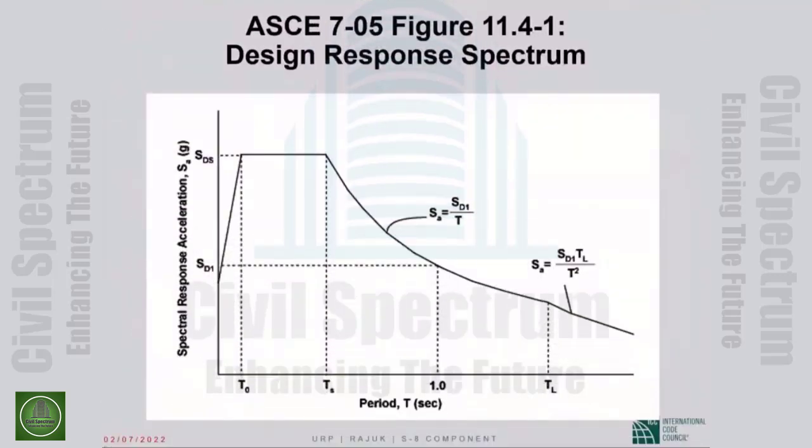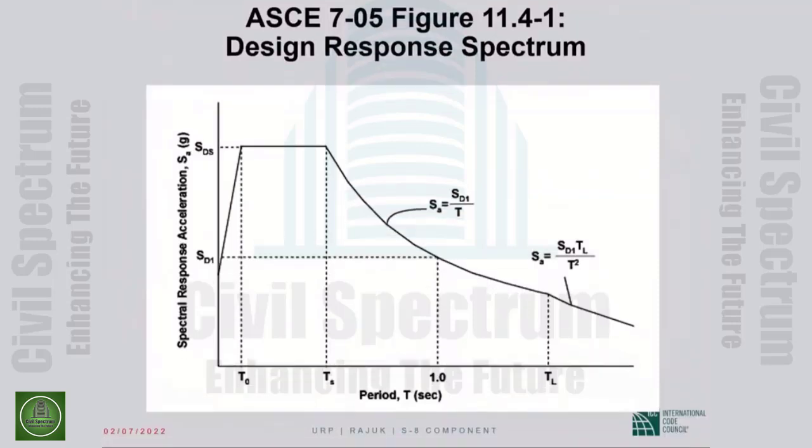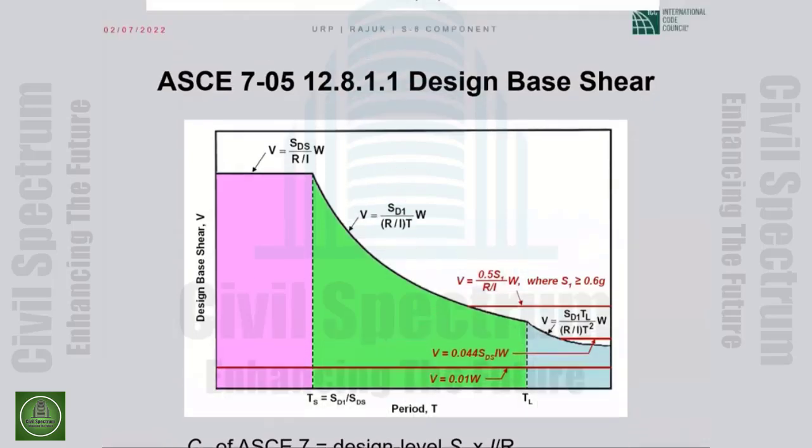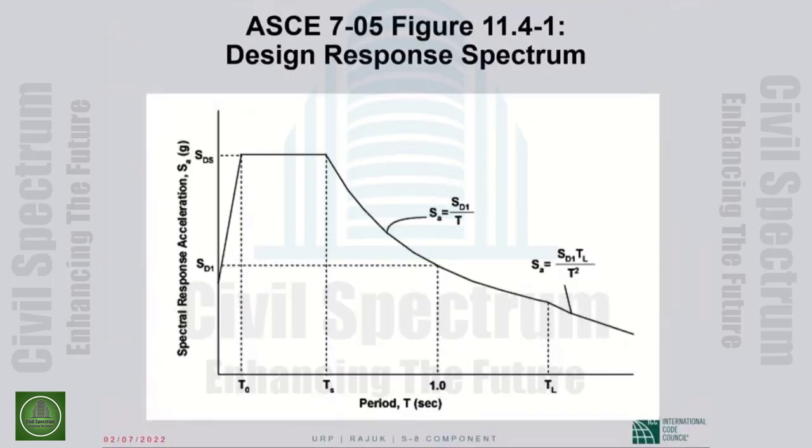Okay, the design response spectrum of ASCE 7 you have seen 10 times by now. The point is, the reason I showed you again is when we do the equivalent lateral force procedure, we modify the elastic response spectrum. This is the elastic design response spectrum of ASCE 7. Design level, elastic spectrum.